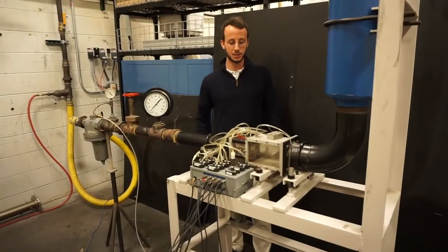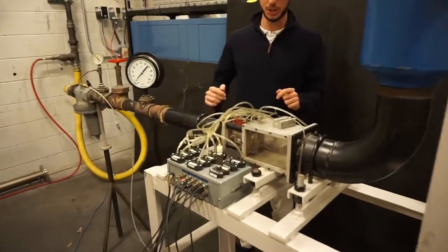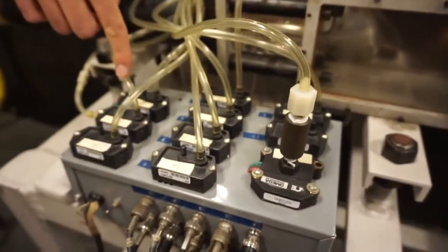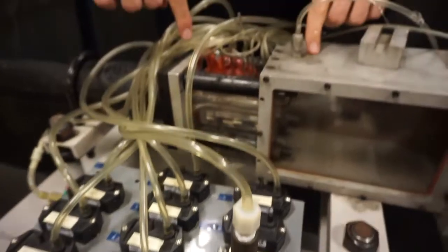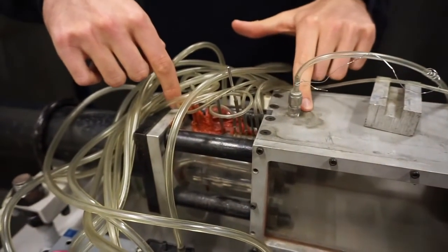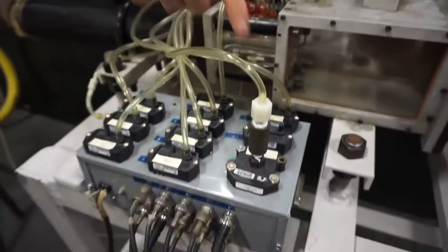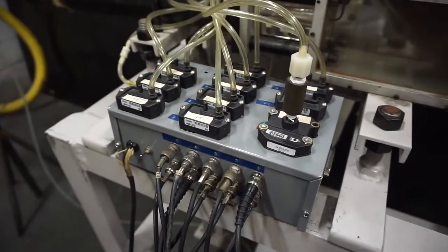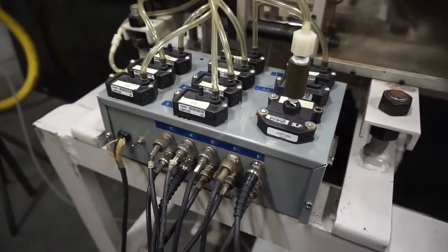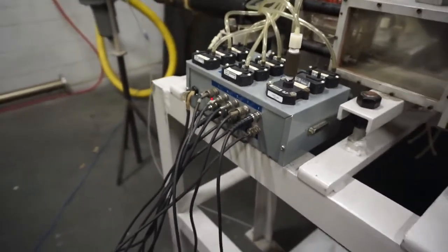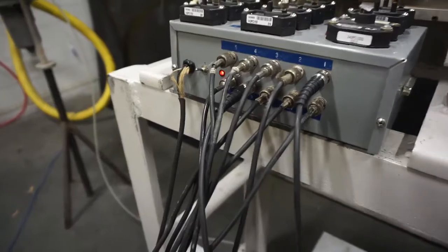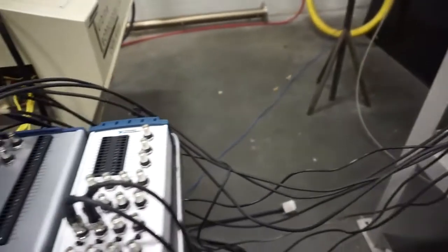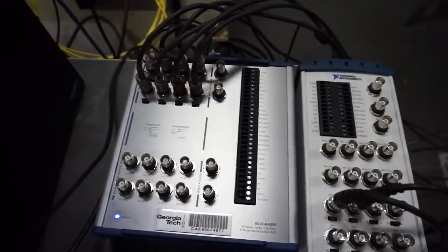The main thing we'll record during this lab is the 8 pressures coming from the pressure taps right there. They are connected to all these pressure transducers. You then have two other pitot probes at the upstream and downstream of the converging diverging nozzle, which are also connected to these two pressure transducers. These are diaphragm type pressure transducers. They give us voltage from the pressure measurements from the pressure taps and the pitot probes. They are then connected to the two National Instruments DAQ boards right there.